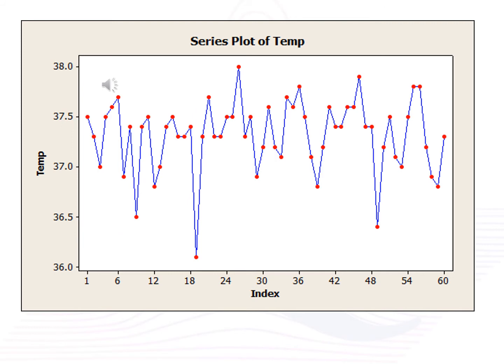Notice here that based on the plot, we indeed have more than 5 distinct values for the data. We can conclude here that we have adequate discrimination for our tool. Now let's take a look at the data and round it to the nearest 1 degree C.